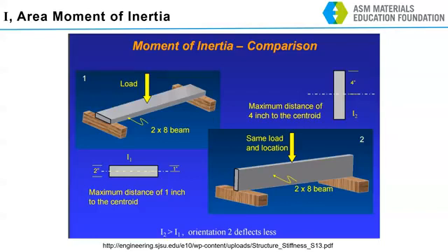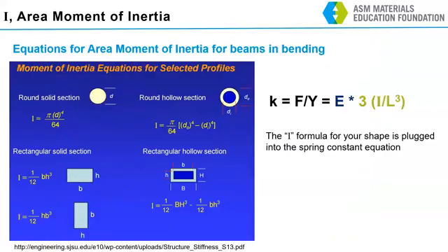Once you've got a good idea of that force, rotate your beam 90 degrees so it looks like figure 2 down here. You're going to put your thumbs in the center of the skinny edge now and try to flex it. What you'll probably observe is that it's much more difficult to flex it in that 90-degree rotated, or I call it the stiffness orientation, compared to diving board orientation. So here's the math that describes what you just felt.